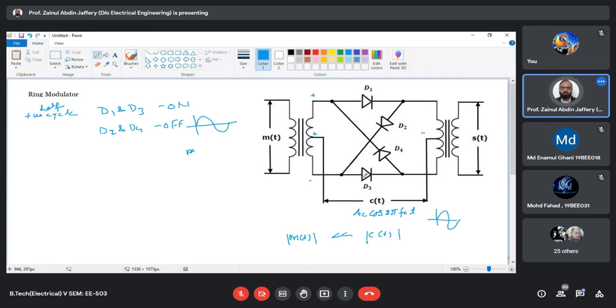So in that way, when they are on condition and they are off condition, so that is open circuits. Okay, so ideally when it is off it is open circuit, and when it is on it is a short circuit. So these have become short. So this output, if we take h(t), so this h(t) will be your m(t), because the voltage that is here is the same voltage you will get here.